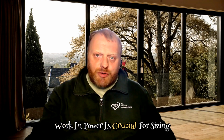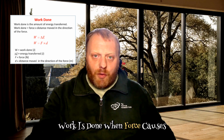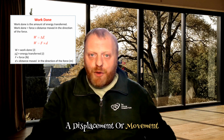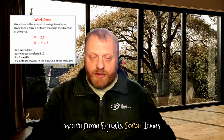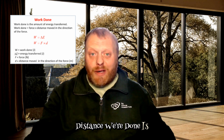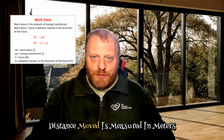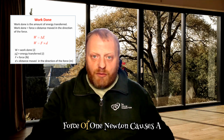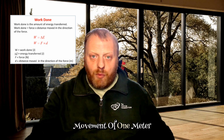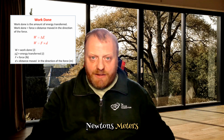Understanding work and power is crucial for sizing equipment and evaluating a system's performance in BSE. Work is done when force causes a displacement or movement. It's expressed as work done equals force times distance. Work done is measured in joules, force is measured in newtons, and distance moved is measured in meters. 1 joule of work is done when a force of 1 newton causes a movement of 1 meter. This means work can also be expressed in newton meters.